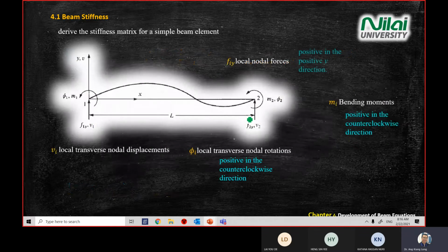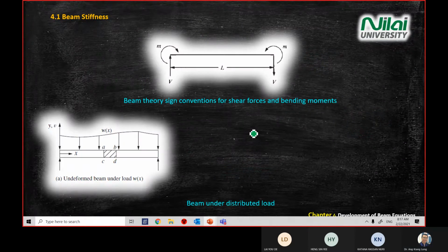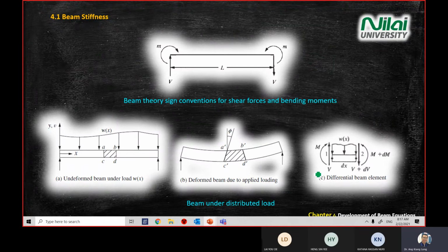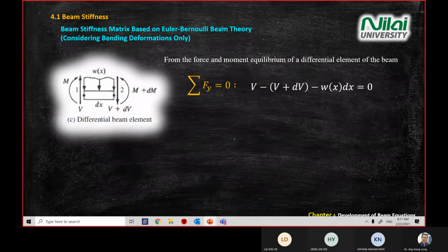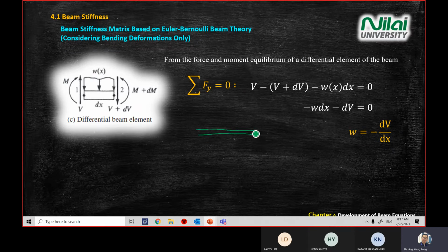All right. So we have covered all this notation, and then we covered a little bit on equations. Based on this free body diagram over here, we arrive at these two equations. First, we take all the force in y direction equal to 0. We arrive at the distributed weight, or load, here. If you have a bar or beam and you have a loading above the structure, and you see this kind of symbol, it means distributed load.